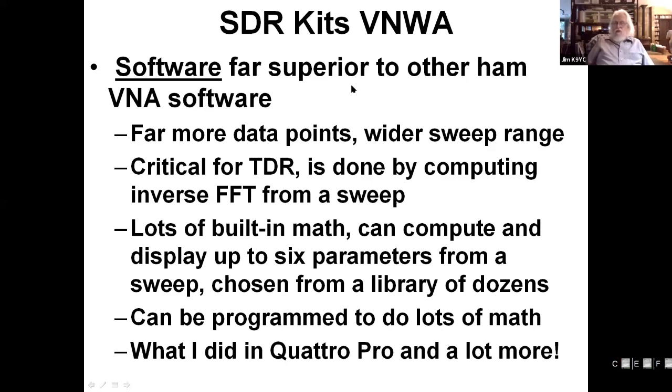Why is it wonderful? Well, a lot more data points, much wider sweep range, which is very critical for doing TDR, time domain reflectometry, to see what's going on in your feed line. And it does TDR by computing an inverse FFT from a single sweep. And you can use multiple windows to get the best view of the data.